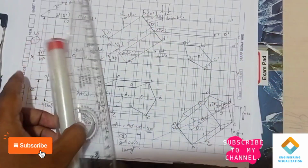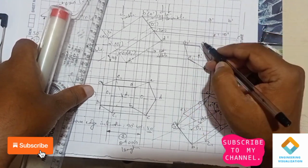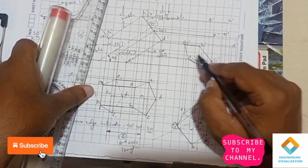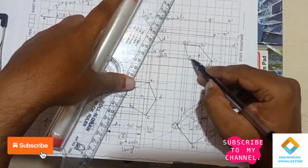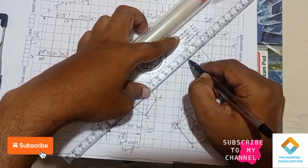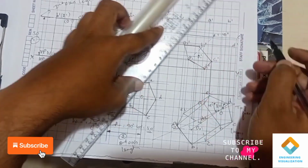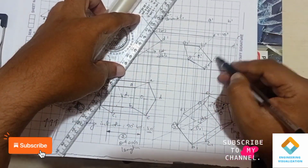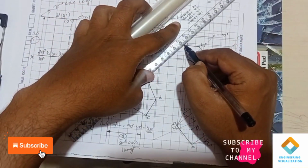Now we can see from the pentagon, when we try to join the vertical edges, the vertical edges which are coming outside of the pentagon are continuous lines. If the vertical edge comes inside of the pentagon, that will be a dashed line. Okay, you can see from E1 dash to E dash, it is passing inside of it. So that's why we are going to draw the dashed line here. The remaining lines will be continuous because all those lines pass outside. I'll be drawing those lines.